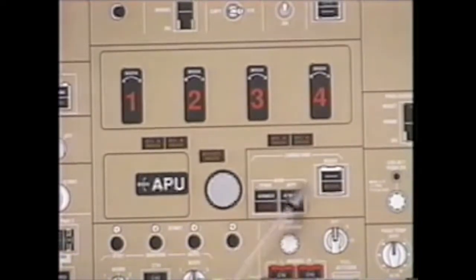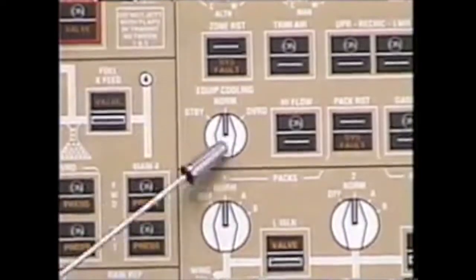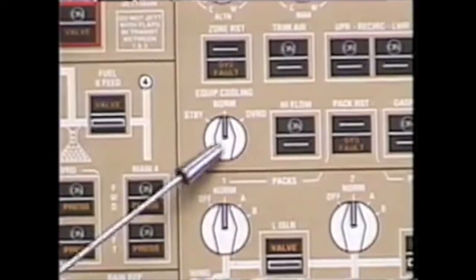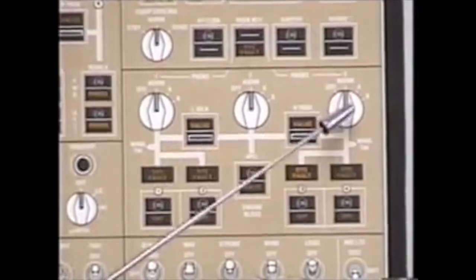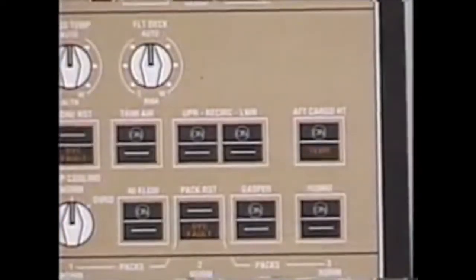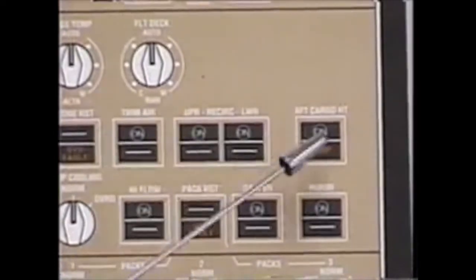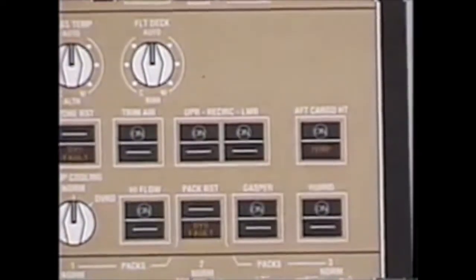Lower cargo, there are 4 bottles in that system referred to as bottles A, B, C, and D. Arming of a cargo fire button, either forward or aft, will accomplish four things, regardless of which switch you push. Arming either forward or aft will arm all four fire bottles and shut off all fans on the airplane. As a result of shutting off the equipment cooling fans, equipment cooling will automatically go to override, as well as shut down pack number 3. In addition, arming the aft cargo button will also shut off aft cargo heat regardless of this switch position.